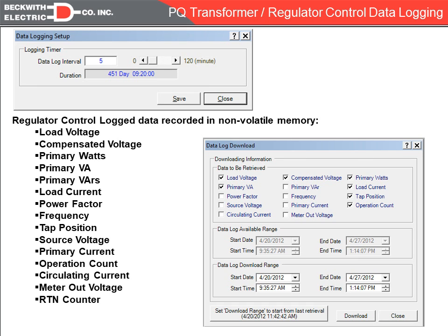data logging. The C had data logging, but it was for much shorter durations. And when you set a duration, let's say 5 minutes, you only had one value for that 5-minute period of time. So for instance, if you were data logging voltage, you would only have one sample during that 5-minute period of time. With the 2001D, we give you 3 points instead of 1. So for a 5-minute duration, you're now going to get the minimum value during that 5 minutes, the maximum value during that 5 minutes, and the average value during that 5 minutes. Now that's not for every point, but it's for many of these points.